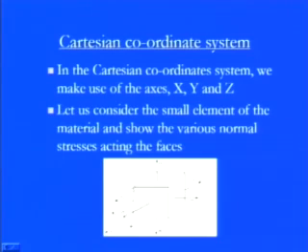Why have we chosen this parallelepiped, or unit cube? Because the cube has 6 faces, and all 6 faces have unit length, and it is symmetrical in all directions. If we are talking about the 3 directions x, y, z, it has 6 faces, so 3 faces are along the x, y, z directions. The frontal side has the same features as the rear part, meaning it is a symmetrical object having unit width, and whatever stress components are there, we can assume